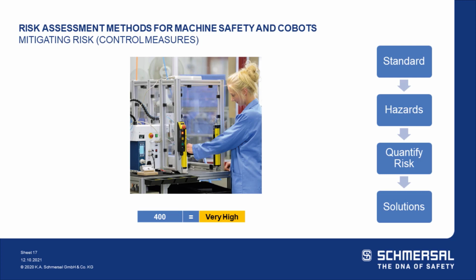Now, again, the amputation example: if the junior engineer presented the safety light curtain as a solution to a knowledgeable risk assessment team, so let's reverse the story. Now we have this team, and the junior engineer came and said, hey, I have a safety light curtain that we can use. There's a much better chance that that knowledgeable assembled team of operators, EH&S, maintenance, or design engineers, would have suggested that the only way a safety light curtain can be used is if there's a way to stop the press from continuing its cycle after the beams were broken, right? Because they know the machine intimately.